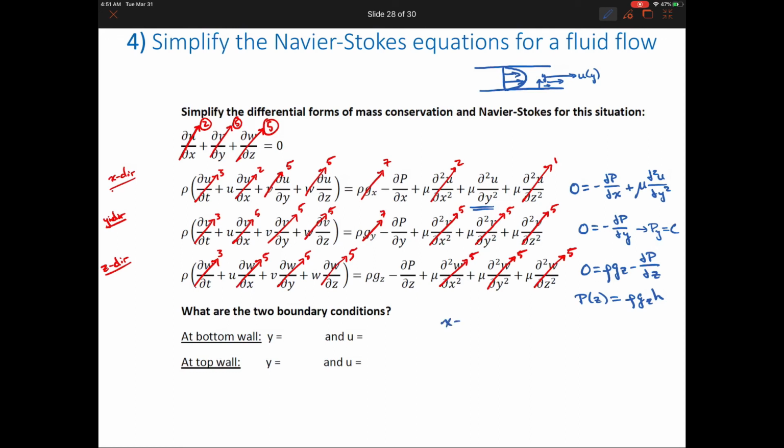So the last real question mark, right, is now in the x direction. So I'm going to leave it to you to figure this out. But what you have now is a statement that is our pressure gradient divided by our dynamic viscosity is equal to the second partial of u with respect to y. And if you work to integrate that, you should come up with a function that describes our x velocity as a function of y. Now you will need to pay attention to what are your boundary conditions.